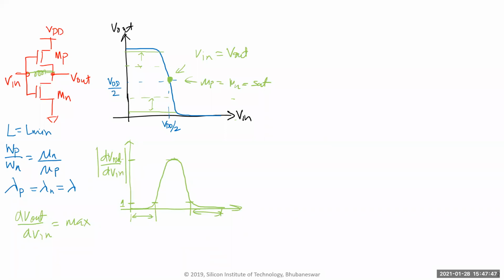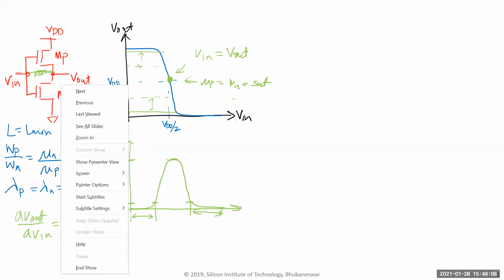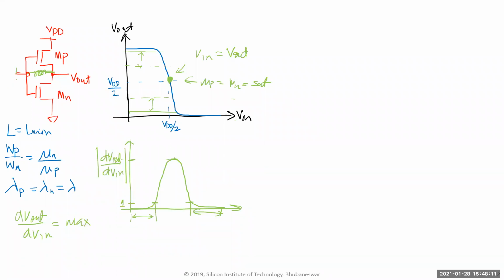Okay. And then for the signal, I don't want to mess up with the signal, because that signal has its own DC value. So I can't join it in DC, but once the AC signal is there, I want to pass it. What kind of passive element will allow me to do that? A capacitor, right? So if I take a capacitor and put it in V in, that's it. That's my amplifier.